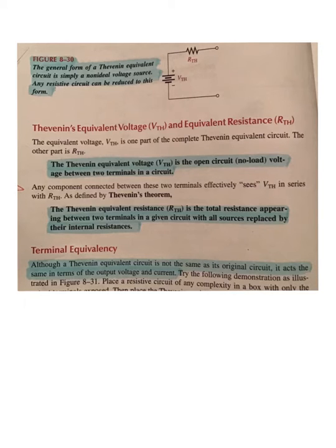The second part of Thevenin's circuit reduction technique involves finding the resistance that the load which you've removed, what resistance does it see? Looking back into this complex circuit, you've got to remember there could be 5, 10, 15 components. There could be resistors, capacitors, inductors later on. And there's also a power supply in the way. And that power supply has resistance. That power supply has impedance.